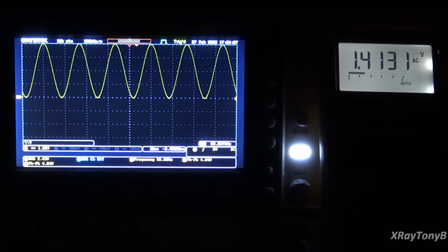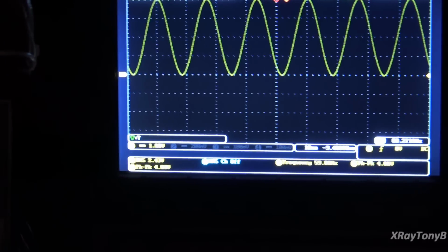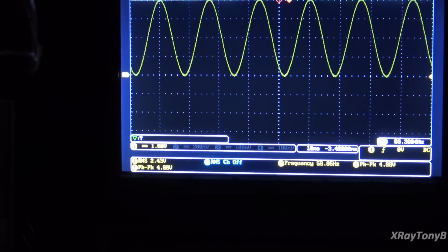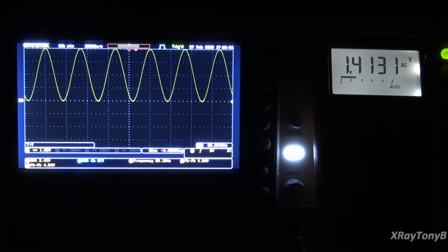However, if you look at the oscilloscope, it's saying 2.43 volts RMS. That's an anomaly of the scope in the way that it's sampling and measuring that voltage. Make sure you stay aware of that, because if you're looking at an offset AC signal and you have a scope that measures RMS voltage this way, know that this can be wrong. And there's your living proof of it. So just something to know that can catch you.